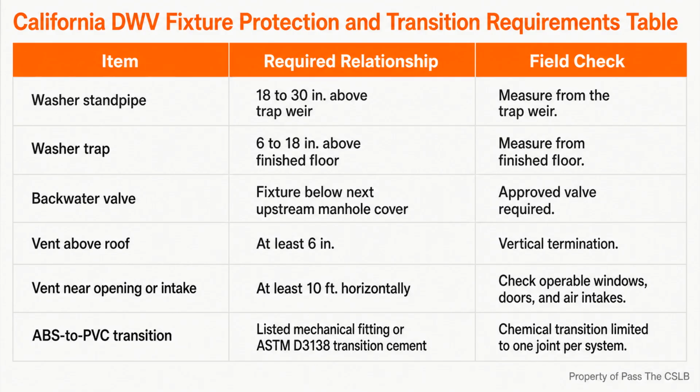Pipe location near the stud face creates a different hazard. When piping is within 1 inch of the exposed framing edge, the report requires a steel nail plate at least 18 gauge thick. The plate protects the hidden pipe from fasteners driven during drywall or finish work. That is a sequencing lesson as much as a plumbing lesson.